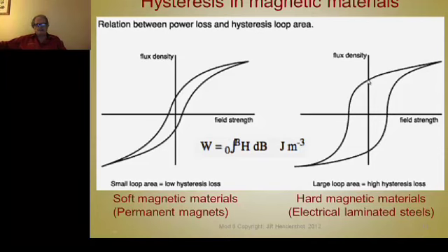That's residual magnetism, isn't it? We like that for a magnet. We want lots of residual magnetism for a magnet, but for a soft iron laminated part of the circuit, we're continuously changing the polarity of it as the motor rotates.